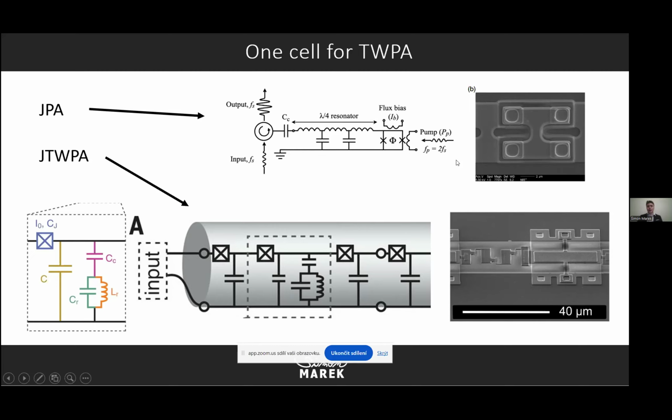So there is a peak in S parameters at one frequency, probably 4 or 6 gigahertz, and there is one big meander there, and oftentimes there is flux bias or pumping of our flux here using some external bias or inductor or trace, whatever it is.